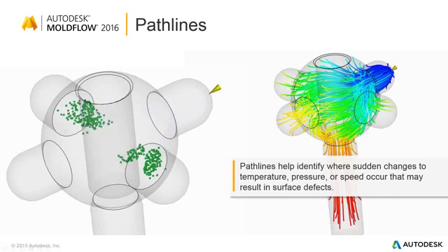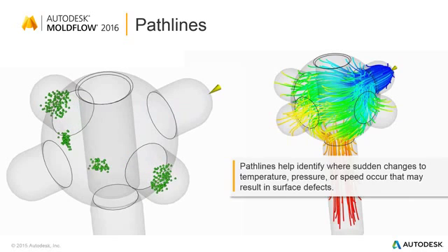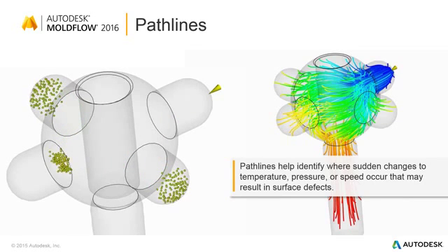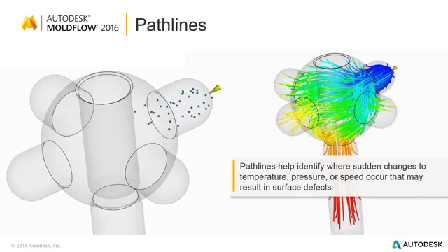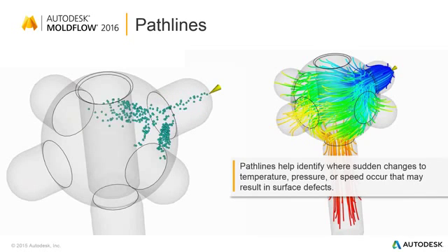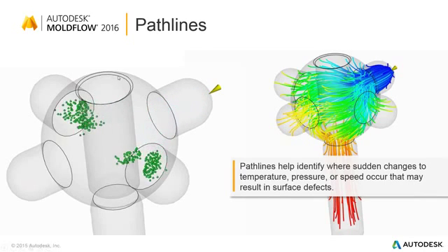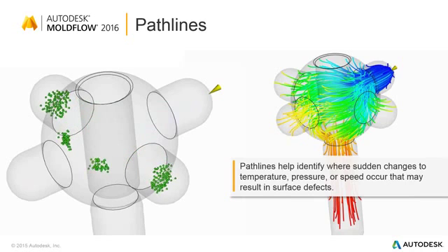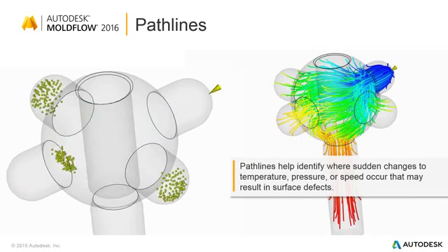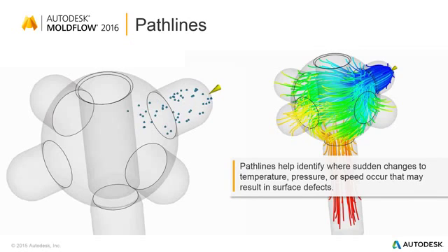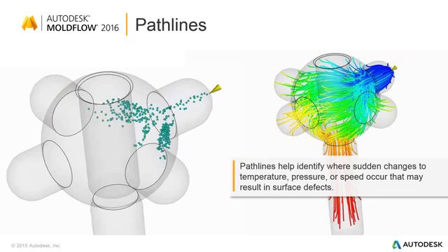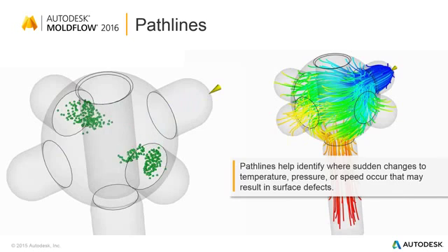So basically we follow markers, or things that represent particles, how they enter the cavity, when they enter the cavity, and how they end up on the part surface. And it gives you very interesting ways to display certain things. In particular, you can see over here how clumps of material, when they enter the cavity, get really stretched, and then how they start consolidating again.